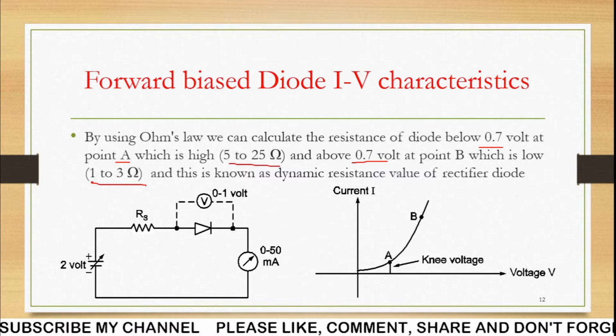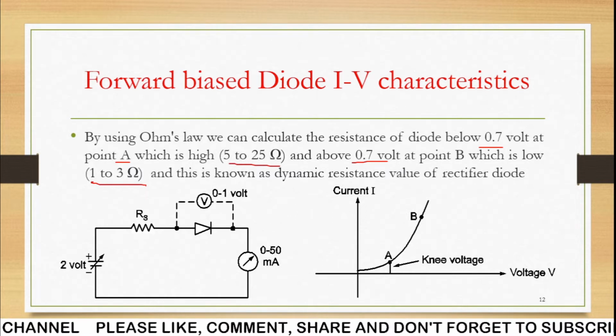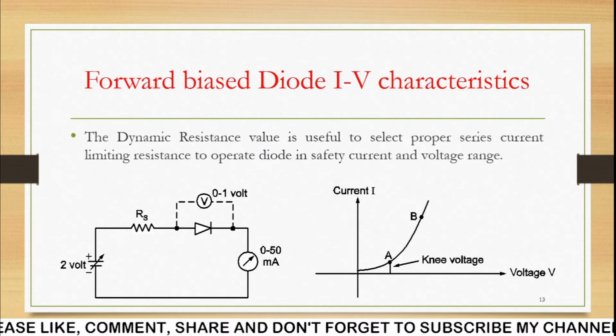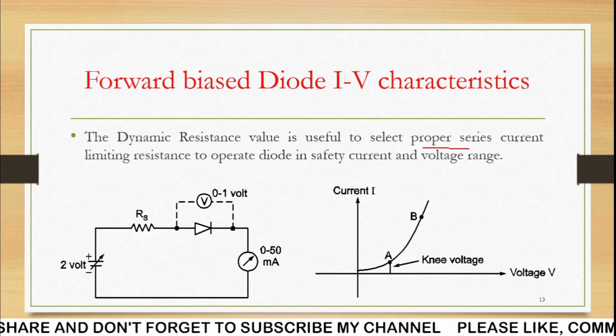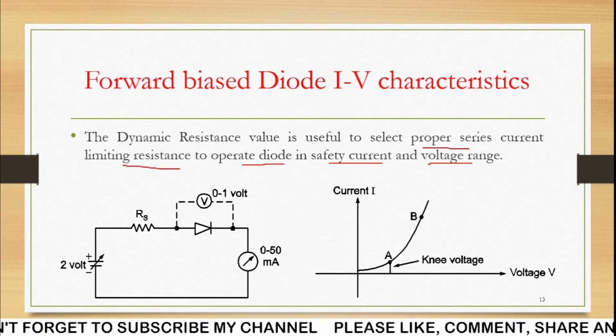We can calculate using PSpice how this dynamic resistance, knee voltage, and the forward bias diode IV characteristic can be drawn. But why is the dynamic resistance very important? Because it is useful to select a proper series current limiting resistor to operate the diode in safe current and voltage ranges.